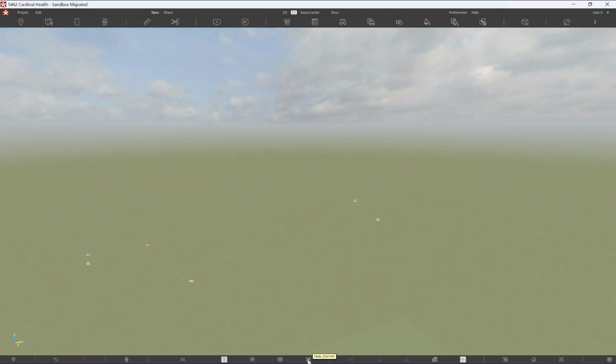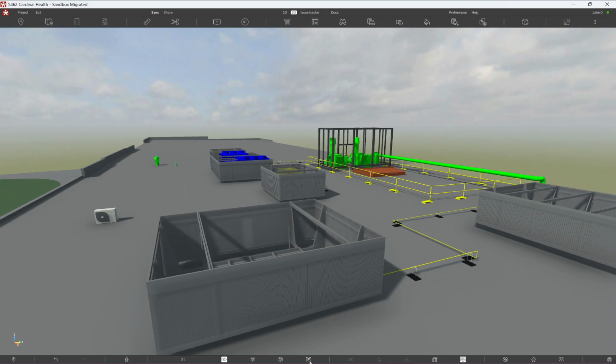Oh, sorry, that's a little laggy right there. So you want to actually click this. It's a box with an eye with the line crossed through it. You will hide it right there. If you want to view it again, just click Show All. Hide, and it's gone. This allows you to see through things like walls. If you want to, hide the wall, you can do that temporarily. And you can also save this as a viewpoint with this RTU hidden. Just go down, create viewpoint, will bring you right here, and the RTU will be hidden. And again, to get it back, all you have to do is just click Show All, and it's back right there.